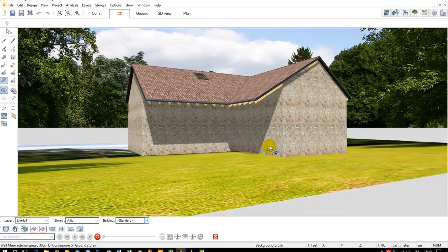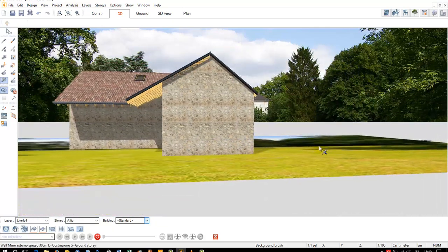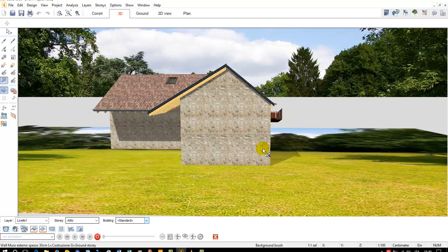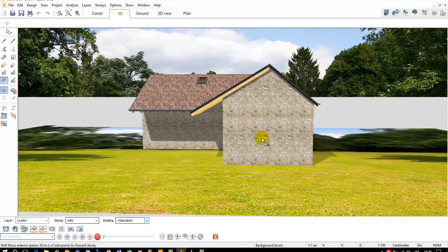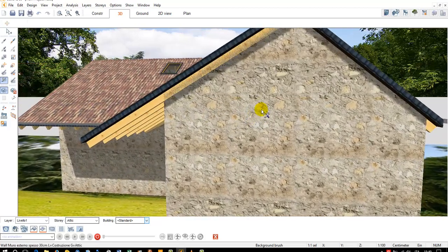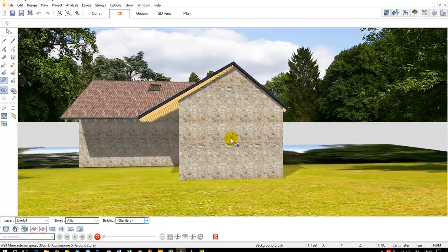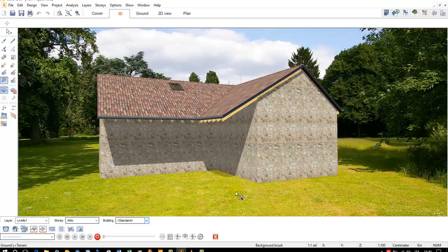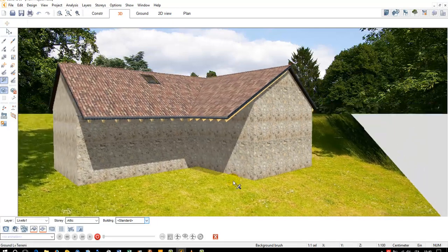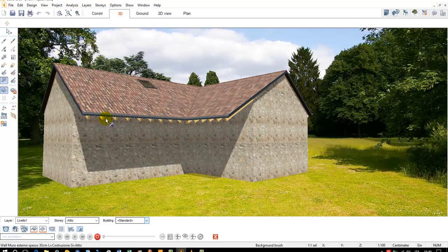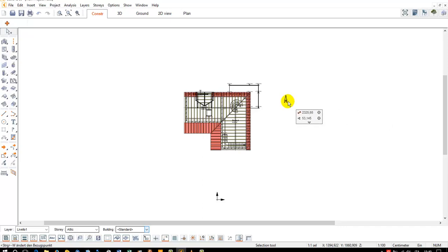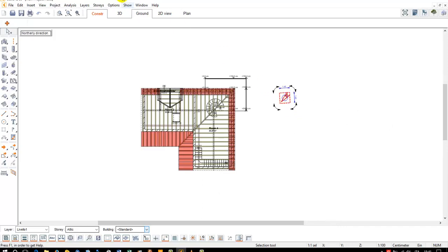So we just go in 3D, we find the right position. We can use page up, page down as the keys. You can click the arrow on the left, on the right. You can use your mouse pointer as a navigator, as a target. Anyway, we find a position, then I click, and you see the house is there. To see the shadow better, I go back, I change the position of the north, I rotate it.